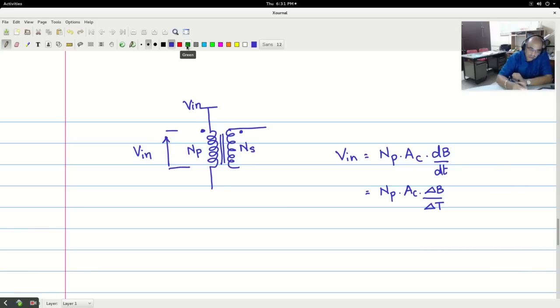Now if you look at the forward converter, we saw the flux phi waveform take a similar wave shape like the current. So we saw that flux went from 0 to phi m, and flux either went in a linear way or in an exponential decay way, depending upon whether it was lossy or lossless, again back to 0. And then after some time, in the next cycle, it again started going in this fashion.